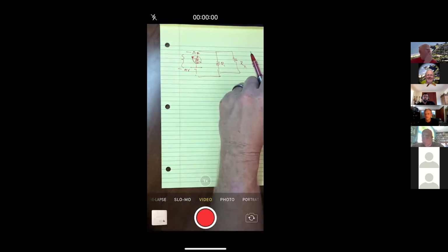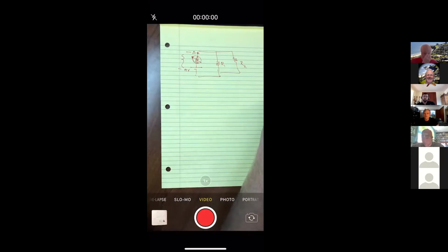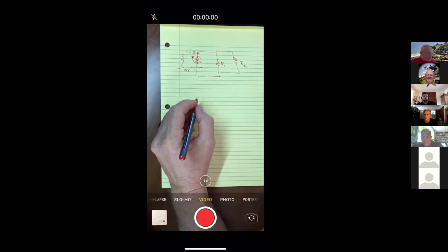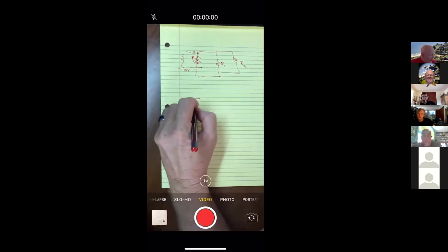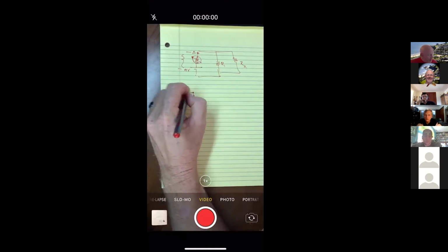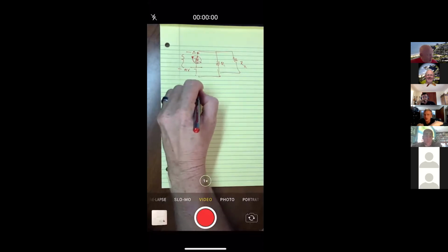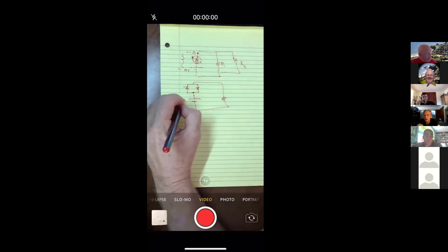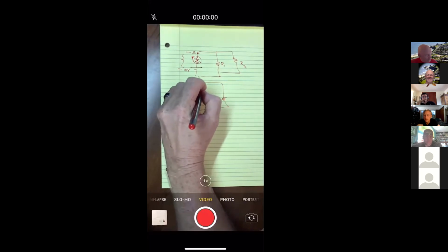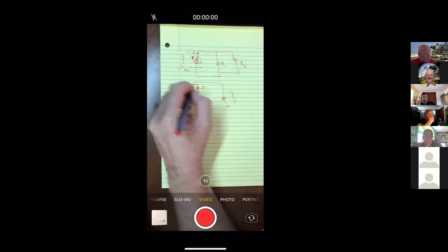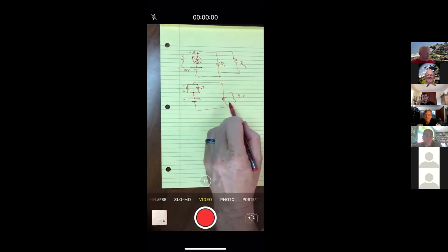What would the effect of hooking those up in, say, parallel or series? Like, would the properties of that apply just like the way they do with resistors? The diodes? Yeah. Well, not quite. In parallel, they're kind of boring because if you hooked it up like this, and then you hooked it to here. So let's say this is 9 volts. You would lose 0.7 here. You would also lose 0.7, but they're not in series. It's just the same voltage. So you would have a power supply of 8.3.